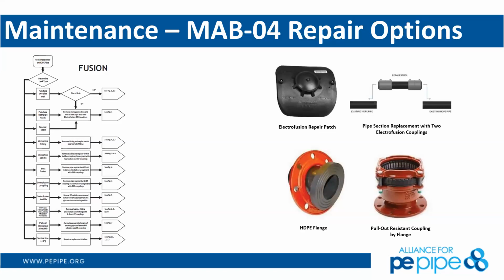Most of the fittings that you work with on a routine basis, that you'd go out in the middle of the night or just after the Super Bowl, as that's a high demand time period, to repair your water main at that time period, can use similar fittings. It is not going to be a fusion fitting unless you specifically go out there with fusion tools, but you can come back at a later date to do that fusion as we go through.